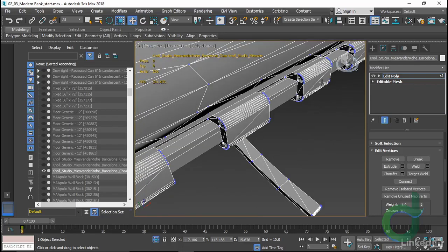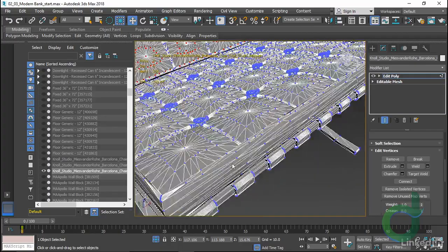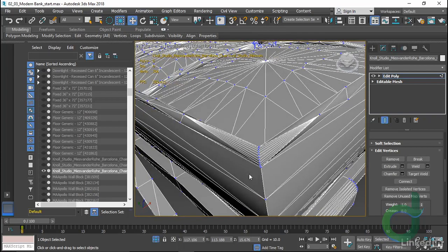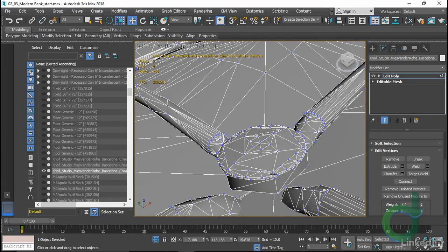take my new one and clone it to the others and replace those elements, reducing down the number of polys considerably. We can also look at the welting. Again, this can be maybe a 12-sided or even 10-sided cylinder along here with a couple of edge loops modeled in and reduce down this poly load considerably. It's also worth a look at things like the buttons. We may end up wanting to replace these with hemispheres that have been scaled down.